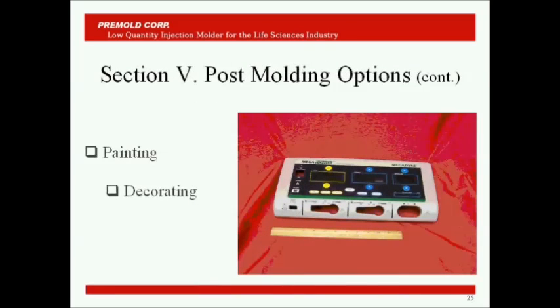RIM molded parts can be painted various cosmetic colors as well, and also different textures. Multicolors and metallic colors are often done. Like all painted materials, surface preparation is the key to getting good, durable coatings on a RIM part. RIM parts can also be decorated using the silk screening or pad printing process.